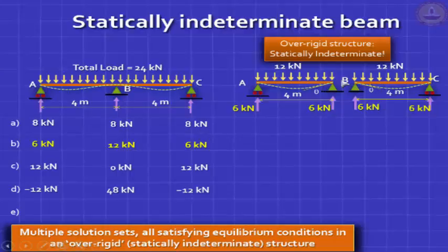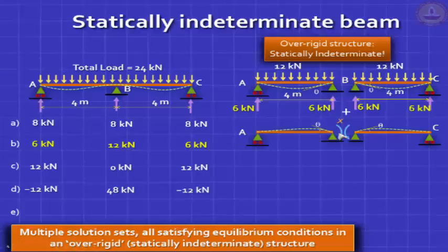To have a 0 slope here, and to maintain continuity, you will find that you get something additional. The additional is a moment on account of the continuity, and the moment alone will cause it to hog, to such an extent that the theta that you get here is completely neutralized. That's compatibility. Now there are ways of calculating x, but don't bother.